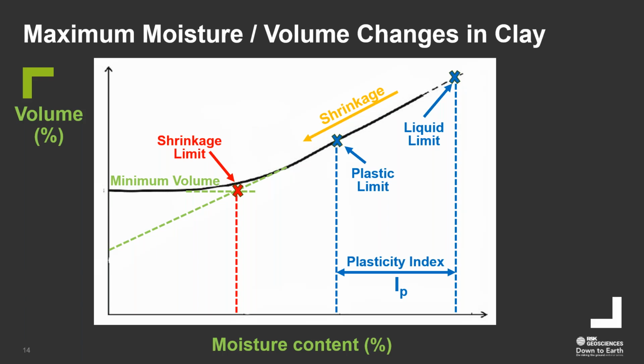Now, how far between the plastic limit and the shrinkage limit will the soil get is the question, really. So one might also talk about shrinkage index, by the way, because some research does indeed talk about that and tries to draw correlations, which also can be useful. And another little thing to just mention is that once you get down to that shrinkage limit area, then we're now talking about this void space within the soil. As you go up towards plastic limit, all of that void space is full of water. So even though we're down at the dry end, it's still actually full of water.